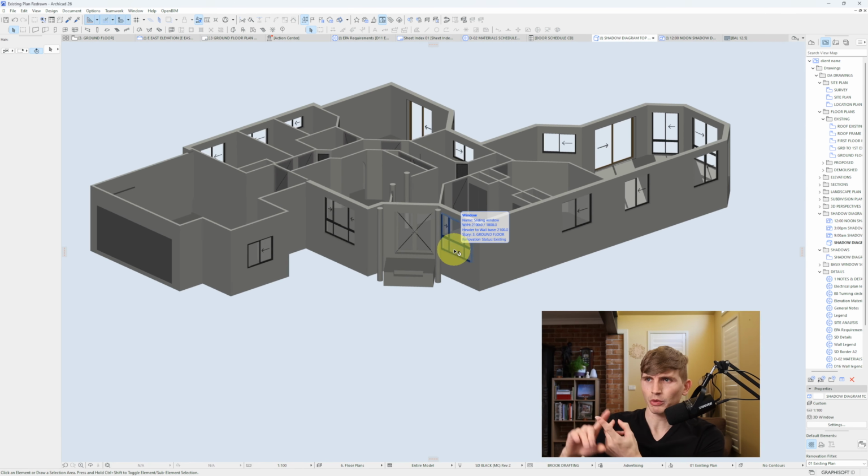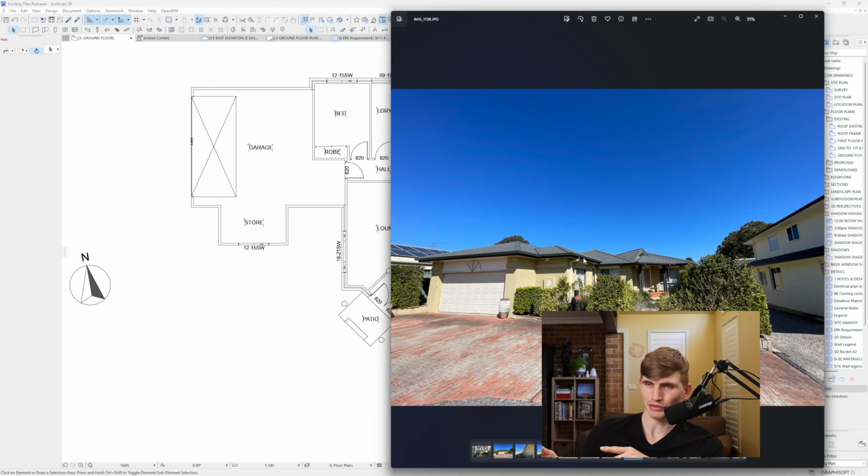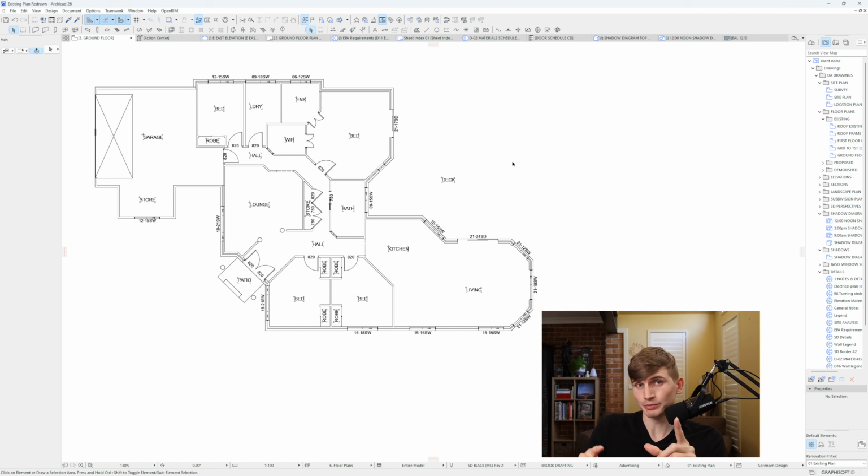All right, so we've got our walls, windows, doors, and slabs, and we've even set them to the correct heights. Next big win that we'll want to get is our roof. The roof for this one is going to be a bit of fun because we've got so many different walls jutting in and out. But if we use the roof tool, it's going to make this so much easier. So let's go to our roof.